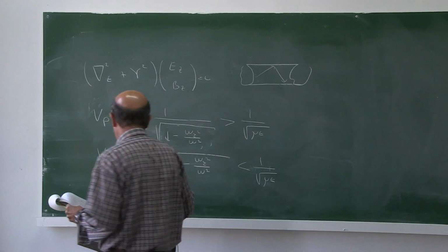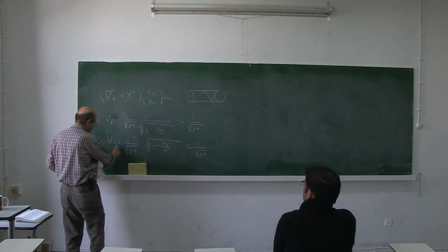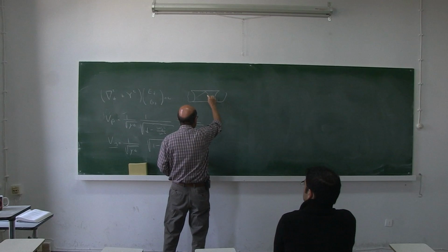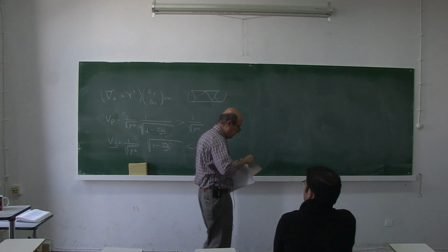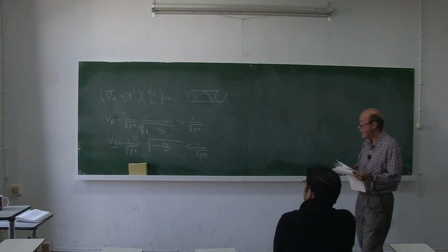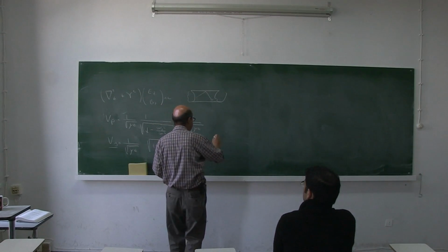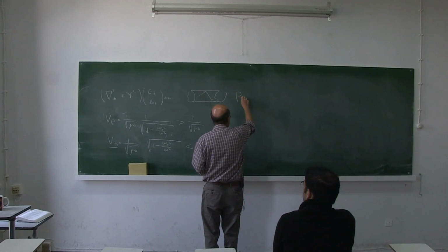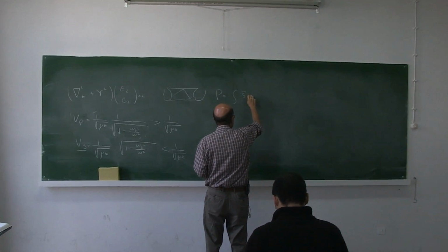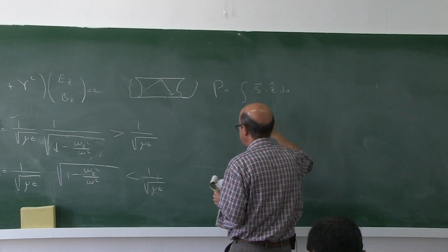So we said last time that the information in the waveguide travels at the group velocity, and that is due to the reflection of the waves from the walls of the waveguide. And we estimate the power transmitted in the waveguide, which is nothing but the Poynting vector dot product with the z-axis integrated over the cross-sectional area.